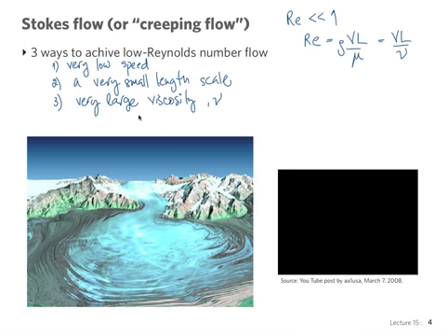Another application of Stokes flow perhaps is things at the micro scale, for example, micro devices that sometimes have a much smaller Reynolds number than 1, or they may have a Reynolds number of the order of 5 or 10, and it's not really creeping flow, but it's still small Reynolds number, and it's still going to be laminar. So anything with low Reynolds numbers like that is going to be laminar. Creeping flow is further down the range of Reynolds number of laminar flow. Laminar, 10, 100, it's going to be laminar, always.